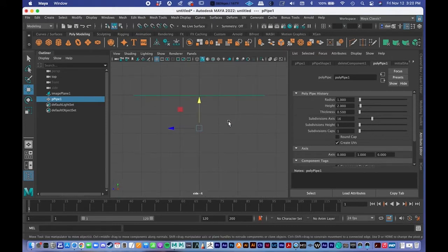And from here, I need to move that anchor point. So if you recall how to move an anchor point, you press D as in dog, to move the anchor point. And you can just place it like that, and that'll probably be good enough. But something I like to do here is I like to hold down X. You see right here, it goes from a square to circle when you hold down X. So again, I press D to move the anchor point, but now I'm holding down X, and it snaps it right to that center point of the grid.